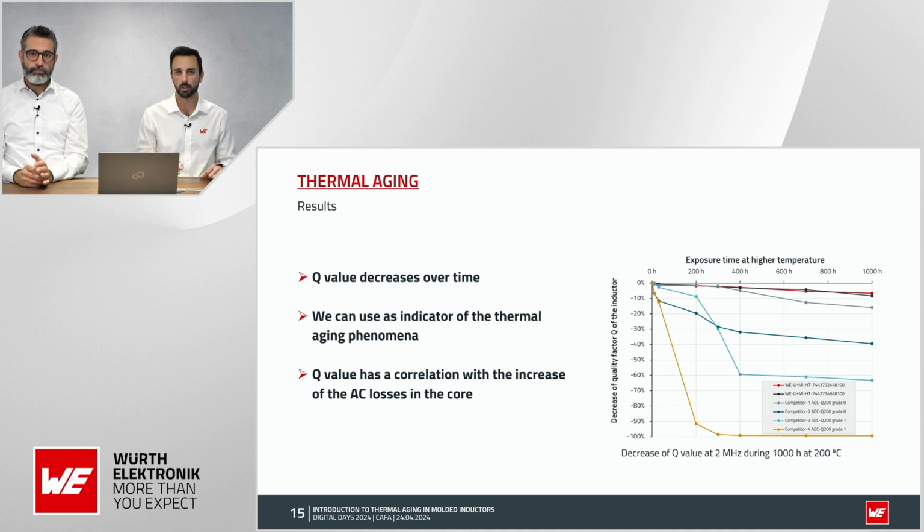We have been running tests for a lot of parts, a lot of different conditions of temperature and time, and we saw a correlation that every time you increase the temperature by 10 degrees, the test time is cut in half.